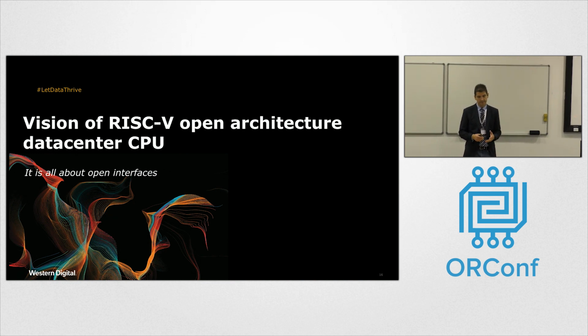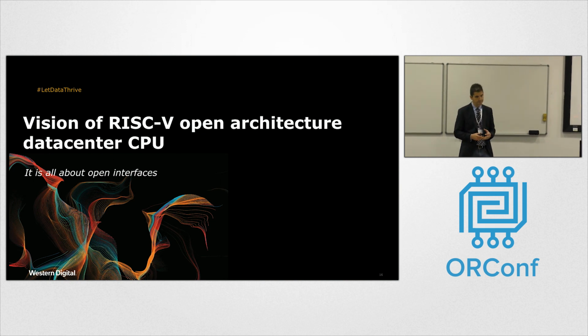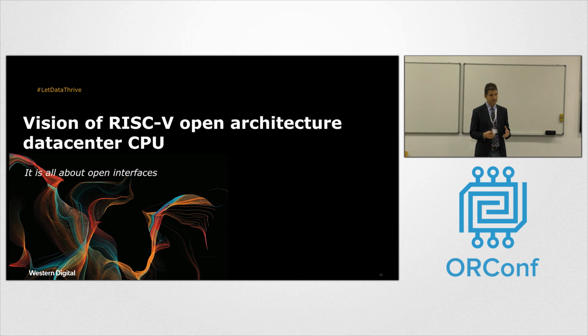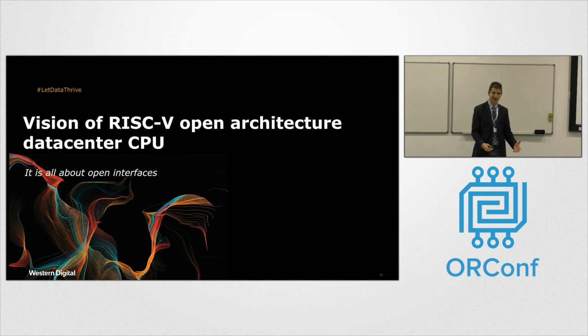At the time, my team in research had built a working FPGA prototype using RapidIO of a cache coherent memory appliance. We wanted an appliance that you can hook up to a cluster and have this memory show up to all the processors in a cache coherent way, so software doesn't have to do any special things. Things just work, and you accept whatever latencies you may incur in the system.